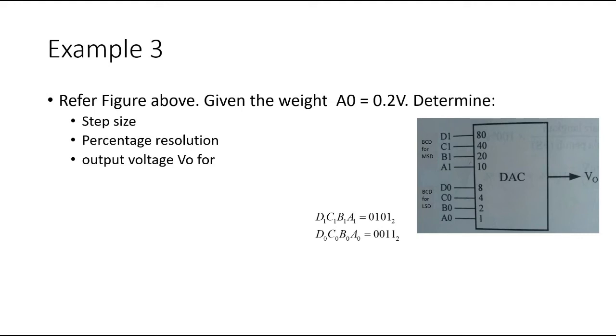Okay, example 3 refers to the figure above. Give the weight A0. Weight A0 is equal to the least significant bit. So A0 equals 0.2, same as the resolution. We can call it resolution or step size. So determine, okay, step size equals 0.2.